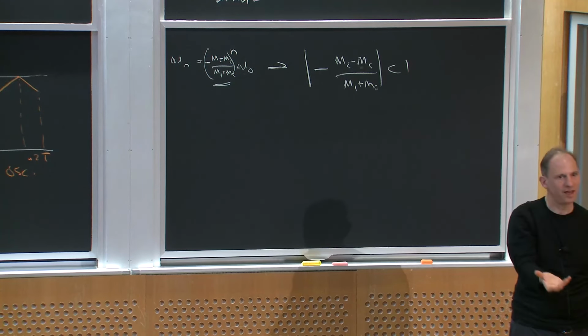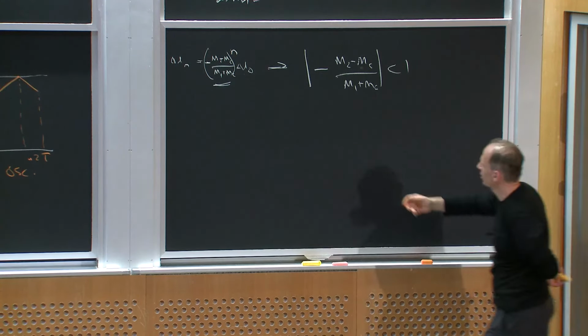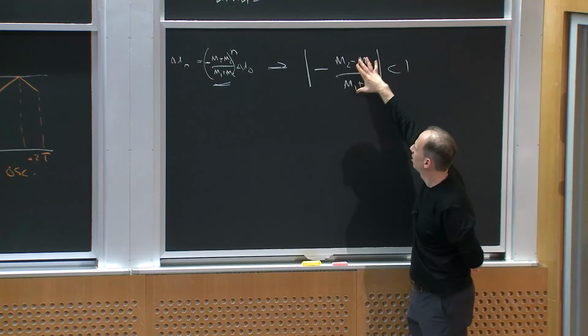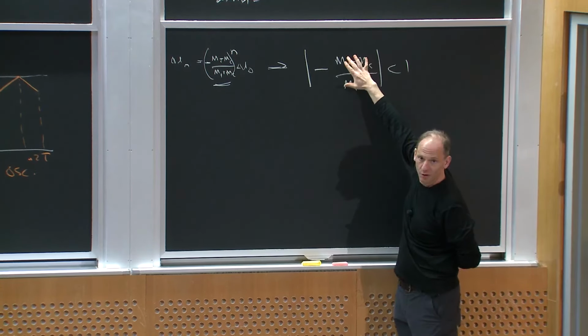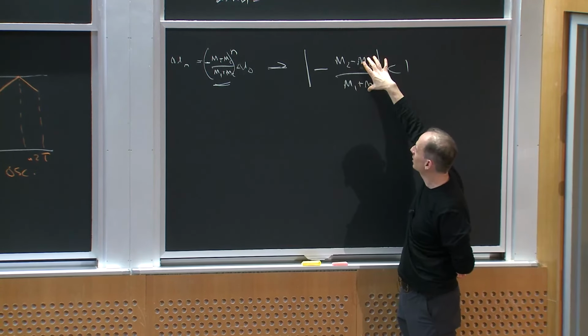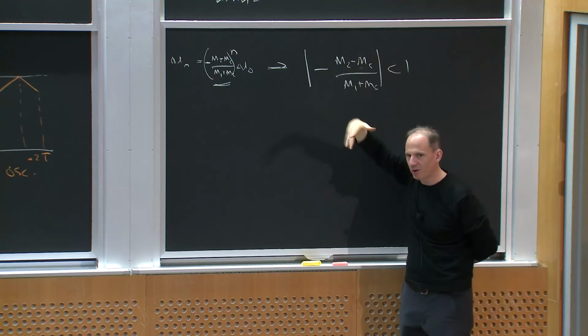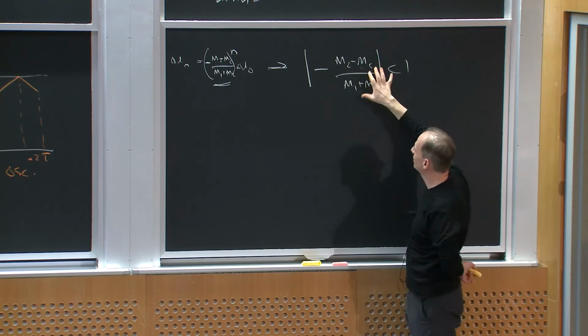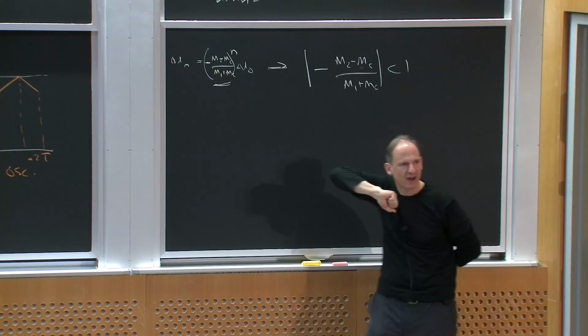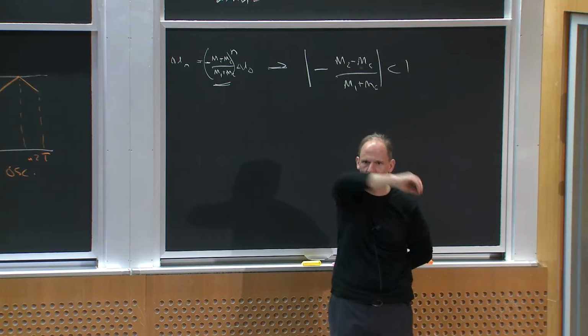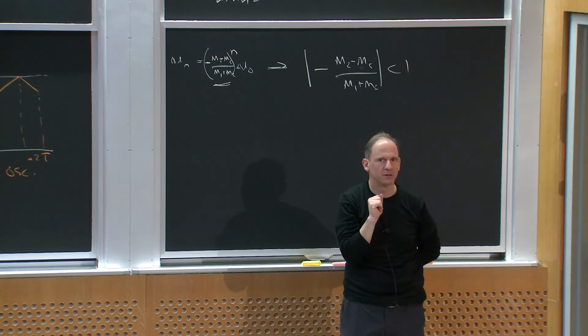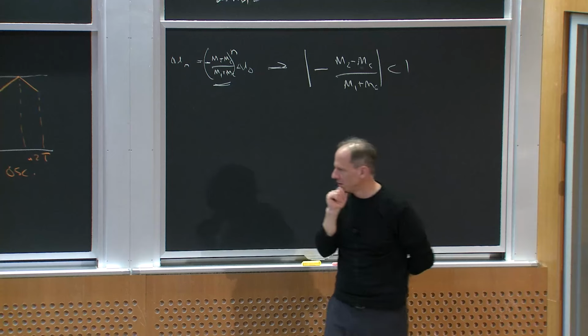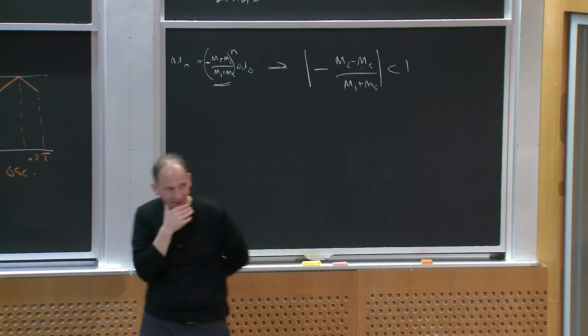So what we'll do then, and it depends on the converter what M1 and M2 are, is pick this compensating ramp slope MC, a positive number, to be big enough that my ripple will decay away in a reasonable number of cycles. Maybe I make this magnitude less than 0.5 or 0.7 or something like that, so it'll settle down. Okay? Any questions about that?